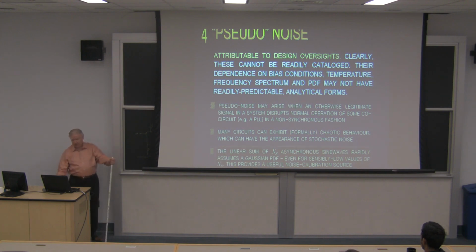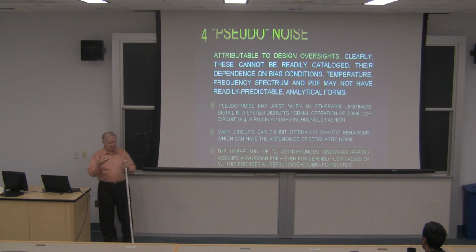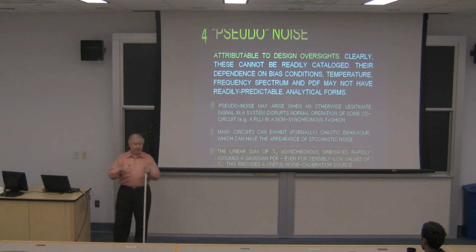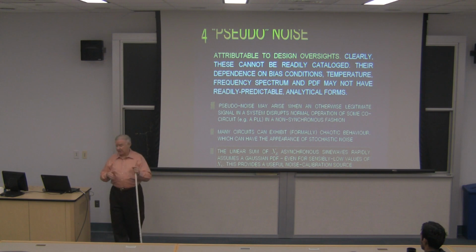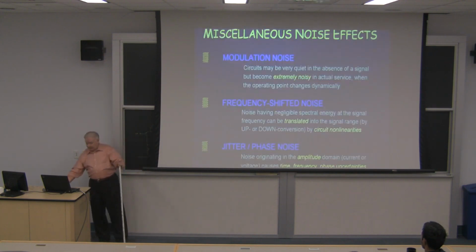One thing I just wanted to point out here is if you want to generate a noise source in time in simulation, just use a summation of a whole bunch of sine waves. I mean, I said earlier that white noise by definition, if you look at the FFT, it's just flat. All of the frequencies are there. Of course, they're not discrete components. But even a few discrete frequencies, let me see. Yeah.